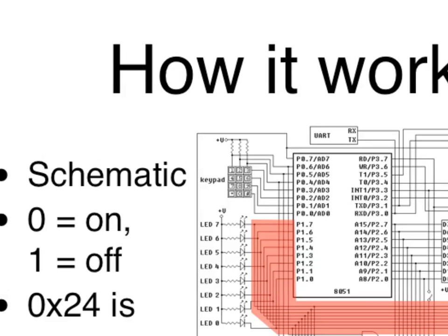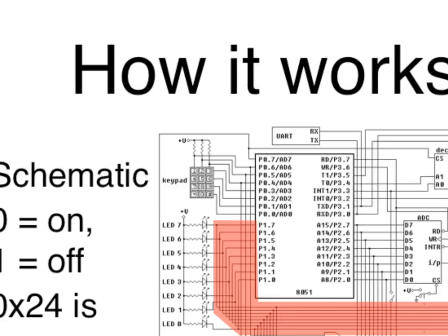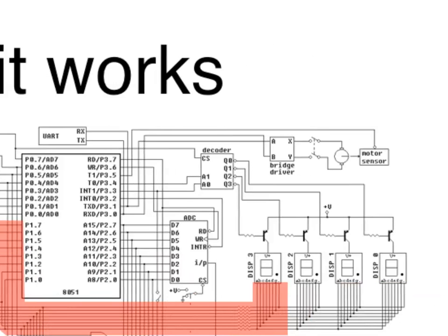Those are the general purpose I/O pins. What that means is if your software writes to some register, then those values will show on the pins. Okay? That's something your traditional microprocessor couldn't do. Remember, if you have registers, you write or read, it's all in software. On the outside, you can't see that, right? But here, these values show on the pins. And so that's what allows you to turn on or turn off the LED segments. Okay? And so those are connected as wires to the 4 boxes there, right?